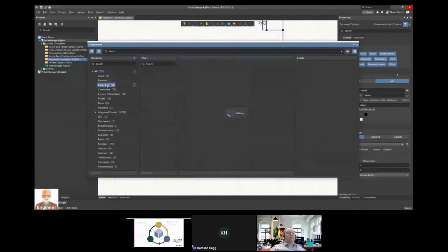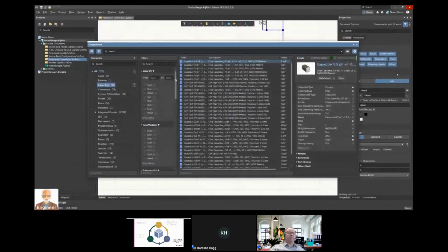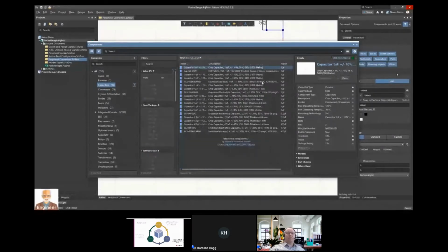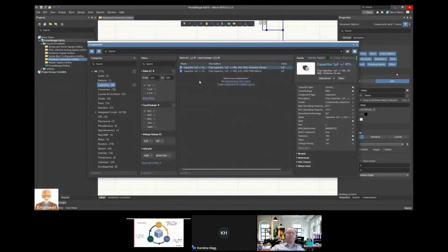We have typed our components, and the type tree is connected to our Windchill system, so the component classification can be driven by Windchill and then just replicated in the design environment. Then we can search components based on their type and technical values, and we can combine technical values when searching. That makes it easy for us to find existing components.